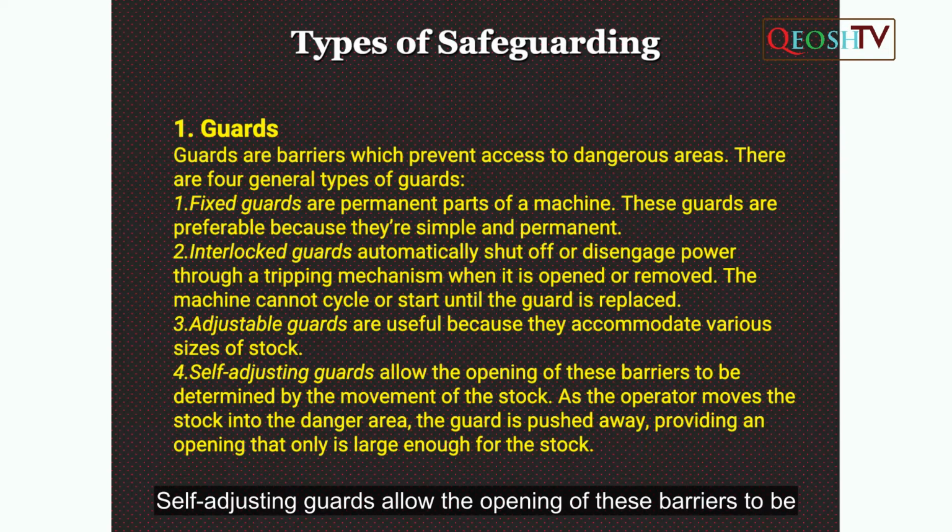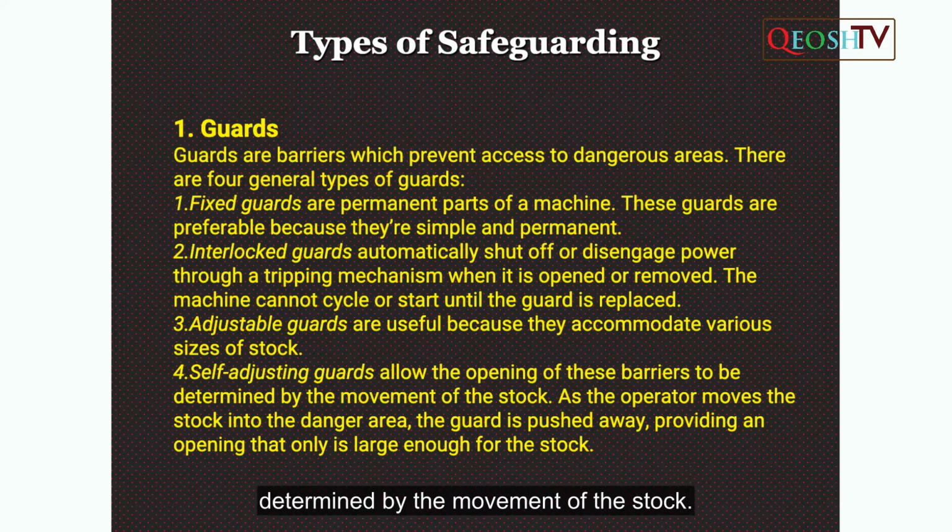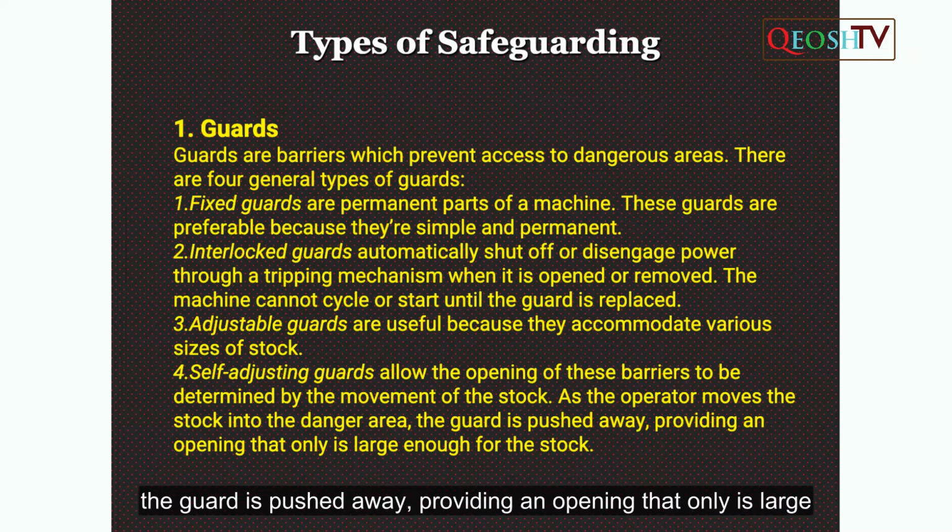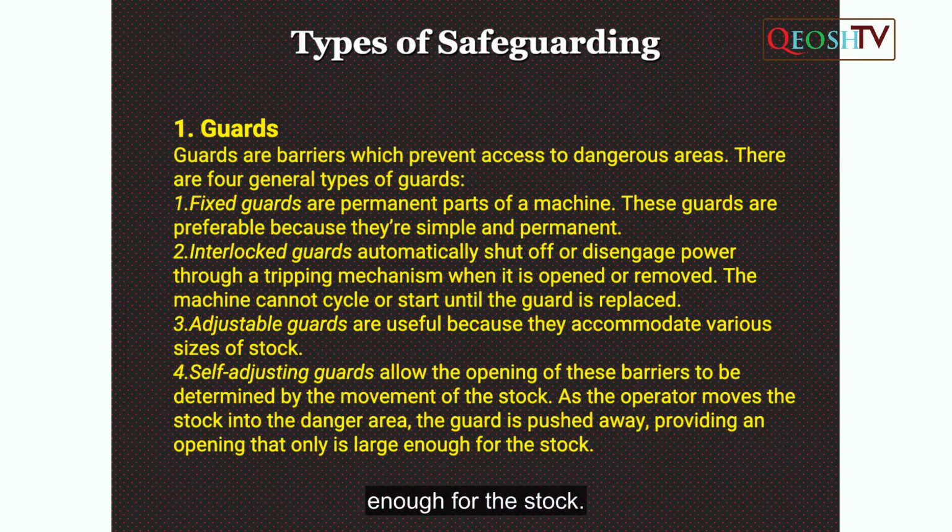Self-adjusting guards allow the opening of these barriers to be determined by the movement of the stock. As the operator moves the stock into the danger area, the guard is pushed away, providing an opening that is only large enough for the stock.